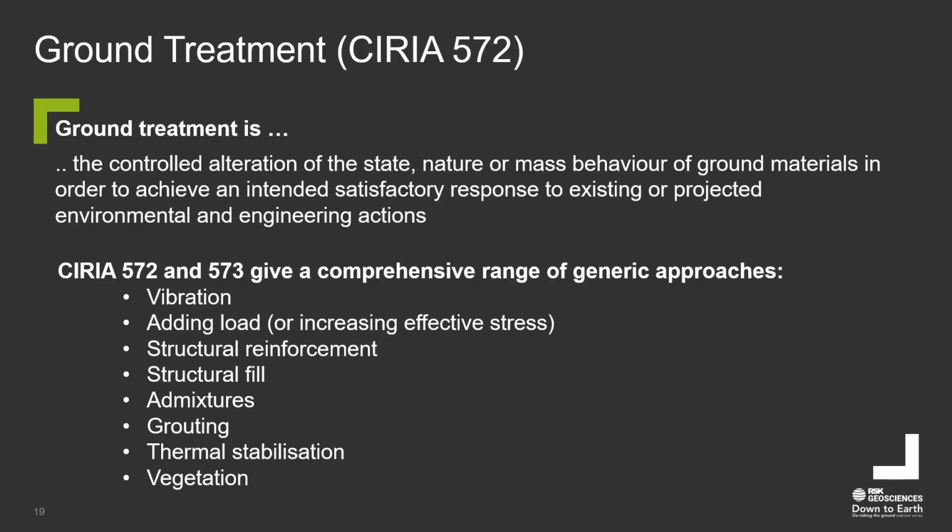Then going through the rest of the list, there's structure reinforcement fill. You can all read the headings yourself. These are all ways of trying to maybe fill the void space, put reinforcement between soil particles, filling in completely with grouting using admixtures, very expensive. Thermal stabilization using heat treatment to form vitrified sort of boundaries, which is a very expensive way of going unless electricity is very cheap. Using vegetation and natural solutions. So all of those in combinations are used on sites.